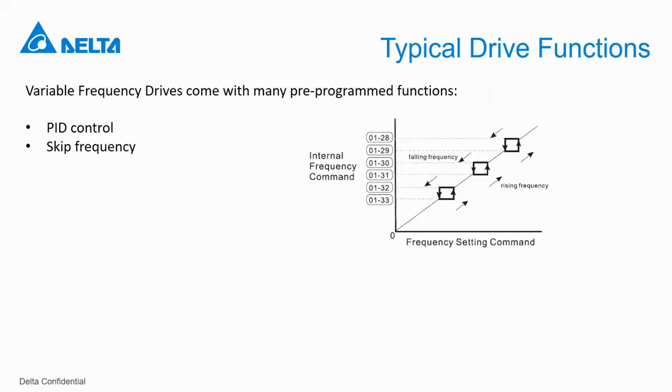So you don't want to give the drive a reverse command and a forward command. You want to do it just with the analog input. For instance, if you give it minus 10 volts, then it runs reverse, and when you give it plus 10 volts, then it runs forward or something like that. If I understand your question correctly, that is possible.